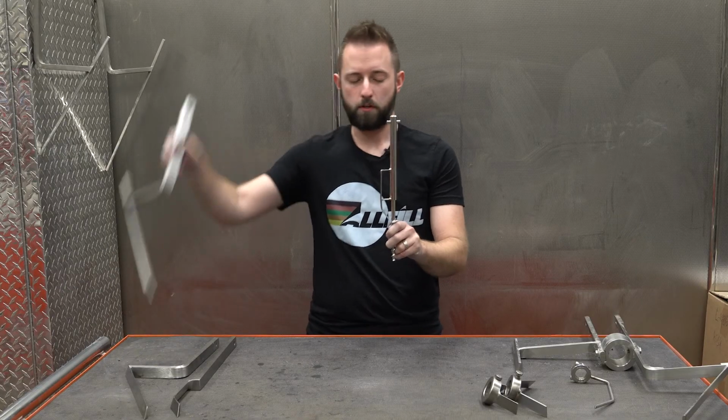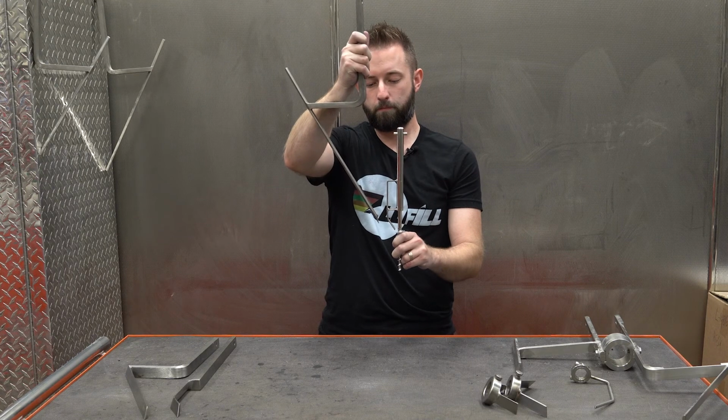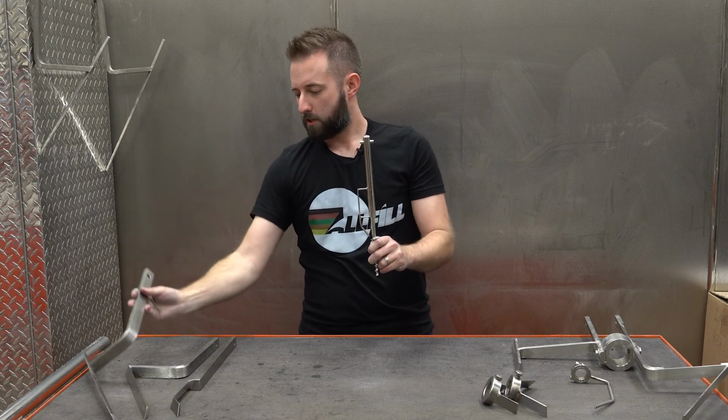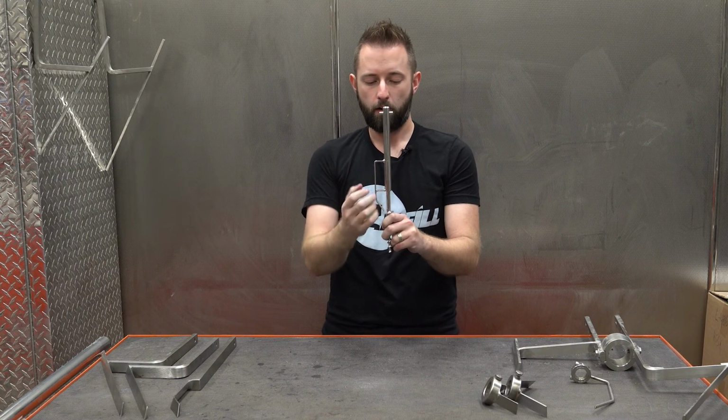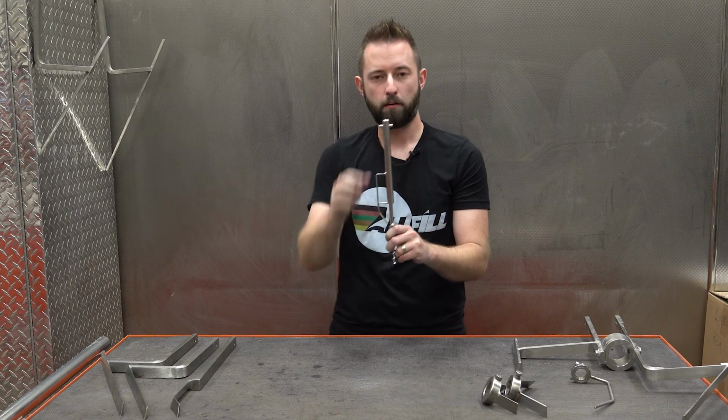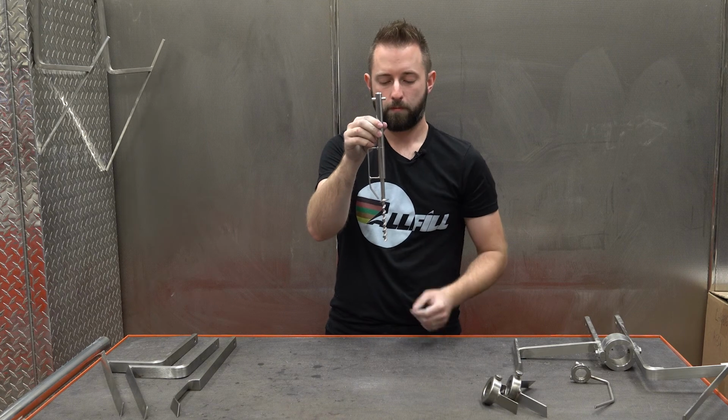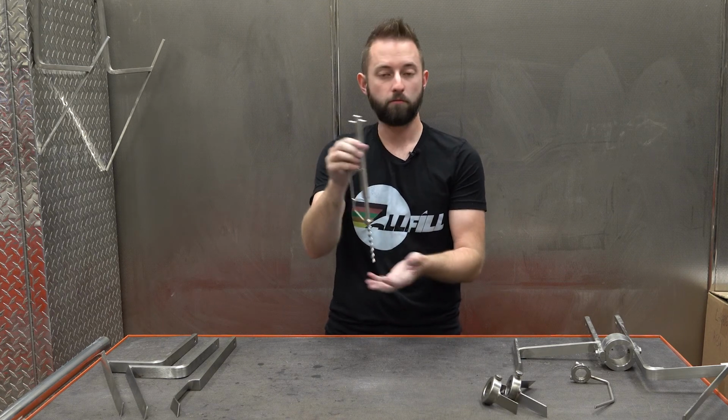So this helps. We can run it in tandem with a slow speed agitation blade. And where the agitation blade cannot reach, this helps to grab that product, aerate it, get it to fall on itself and collapse down into the auger overflight, and then be drawn down through the flighting, yielding a very efficient auger.